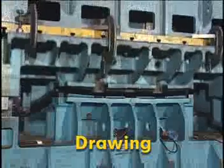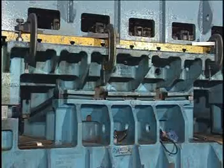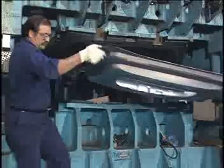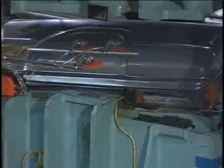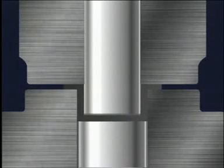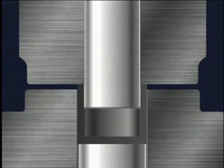Drawing shapes a flat pre-cut metal blank by forcing it into a die cavity with a punch without excessive wrinkling, thinning, or fracturing of the metal. Various complex forms may be produced by drawing. Drawn parts may vary in size from small parts up to aircraft and automotive parts large enough to require mechanical handling equipment. For properly draw-formed parts, the force exerted by the punch must be great enough to draw the metal over the edge of the die opening and into the die.